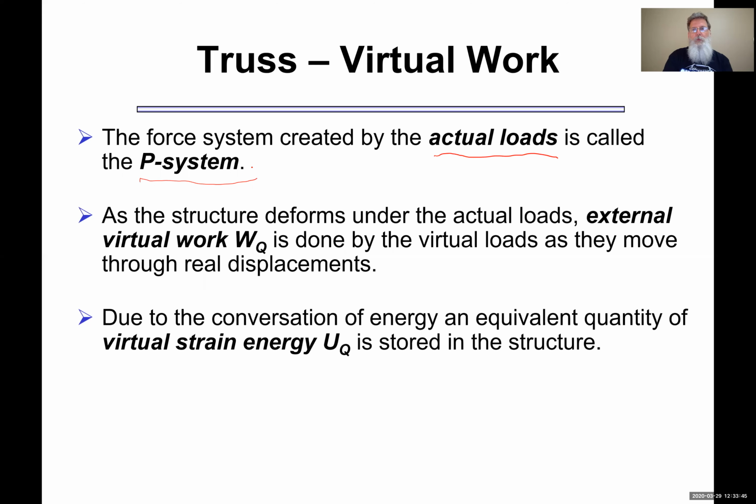So as you apply work to a system, as most elastic systems do, deformable bodies do, they will respond by displacing. And displacement is effectively strain energy. So we're balancing the external work done by the forces with the internal work stored in the system. And we'll assume that's a conservation.